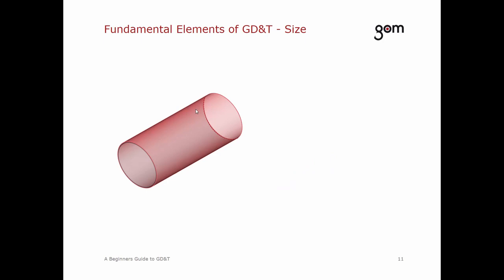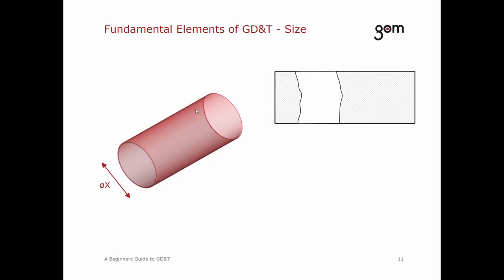Imagine you have an inner cylinder like described in the previous animation. The bolt must fit through the borehole at any point. If the borehole is simply too small, the bolt cannot fit through. So it is important in this case to determine the minimum diameter to find the smallest hole of the borehole. And in order to find the smallest diameter, it is therefore important to have data available for the entire cylinder barrel. This also means that the element needs to be captured entirely, regardless of your measuring system.